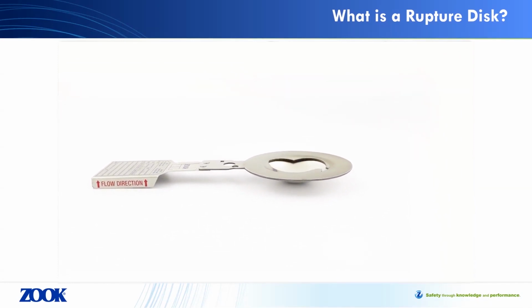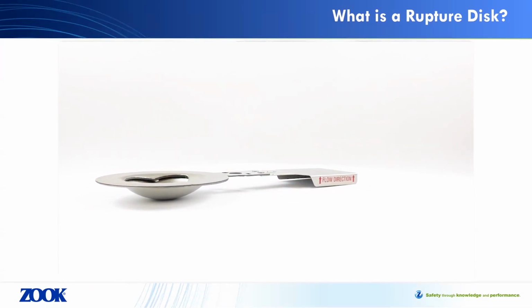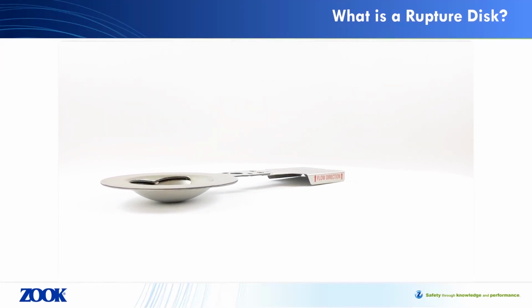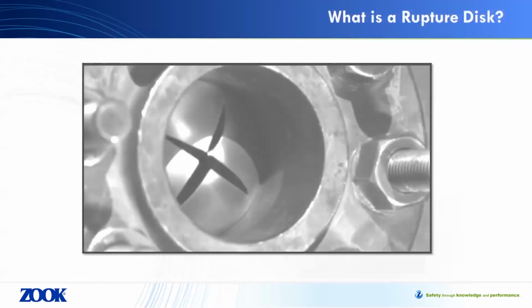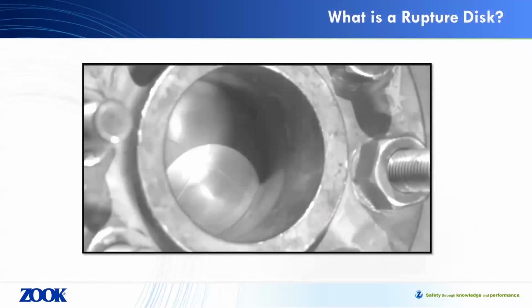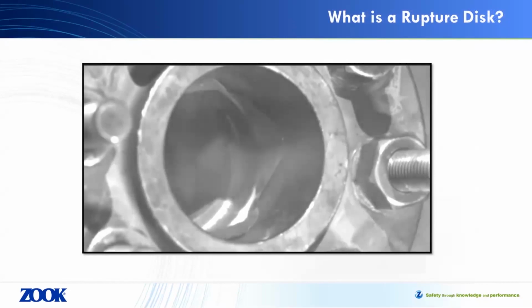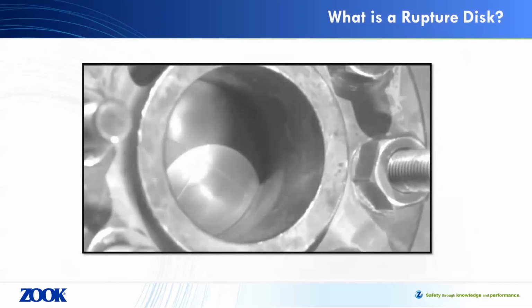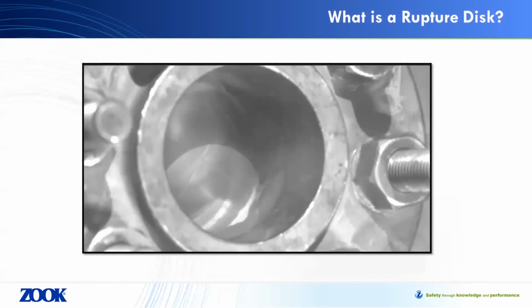The best analogy that I have to offer when thinking of what a rupture disc does is to think about a pressurized system's similarities to that of an electrical system. Everyone is familiar with a fuse or circuit breaker panel installed in their home, workplace, or car. The purpose of this fuse is to protect from an overcurrent event. We can think of a rupture disc as a fuse in a fuse panel. When a fuse is exposed to more current than it's rated to, the excess current causes the fuse to melt and the circuit breaker to become open and not allow additional energy to build up. A rupture disc reacts in very much the same way in a pressurized system, allowing the system to vent and not continue to build pressure to an unsafe level.